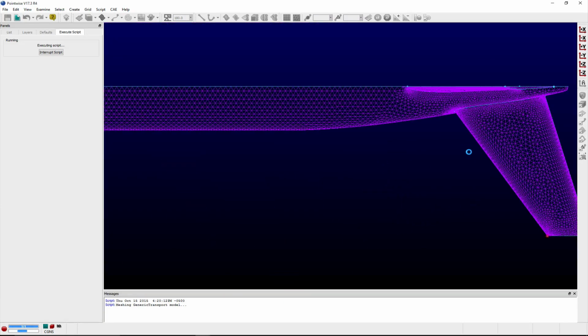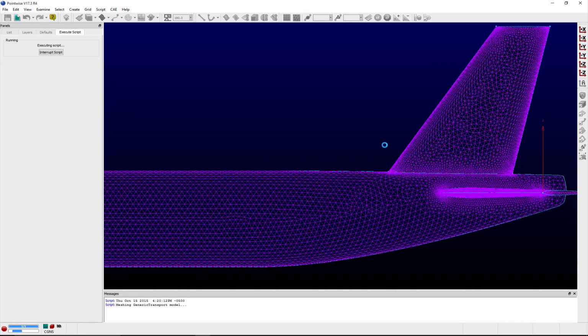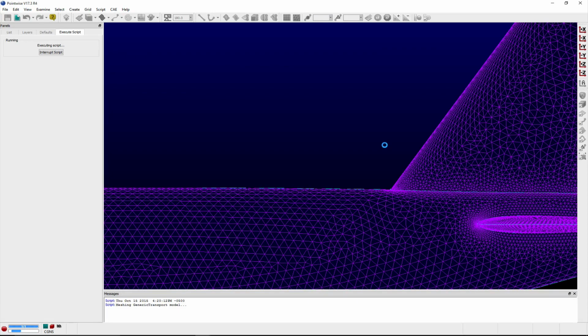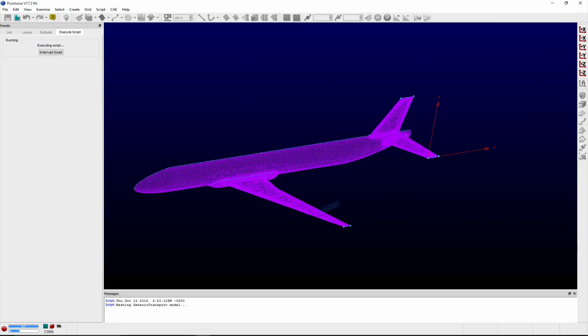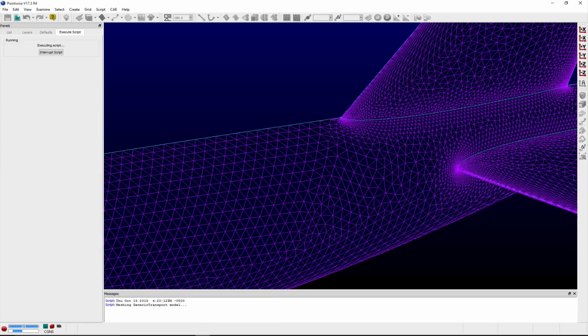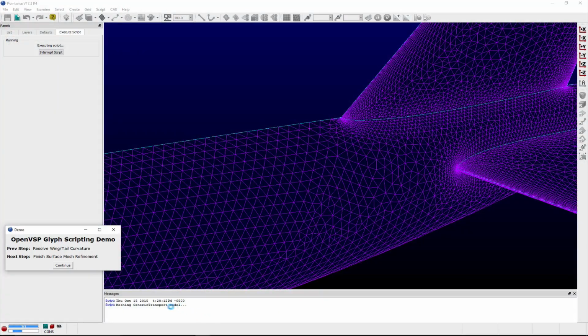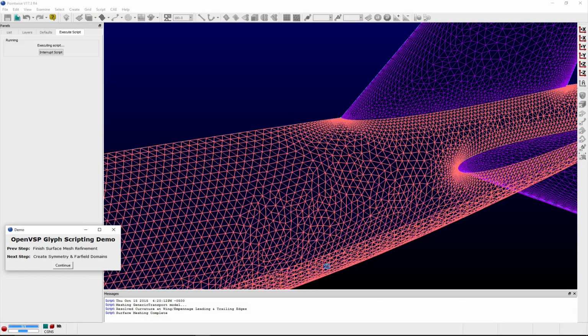Before the surface mesh is completed, unstructured domains along the trailing edges are replaced with structured domains that are then triangulated to help reduce any large area ratios in these regions of the mesh. The end spacing of connectors adjacent to the vertical tail are also updated to be consistent with the spacing changes made earlier when the growth distribution along the vertical tail leading and trailing edge connectors was applied.